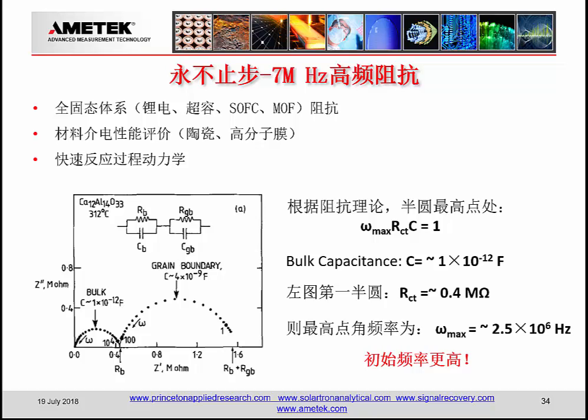We can take this here and scale out, and as you look at the Nyquist plots, the impedance spectra, as you look at these different materials, the capacitance is so low that we need to really push it out to a higher frequency to get the full characterization of the high frequency semicircle.